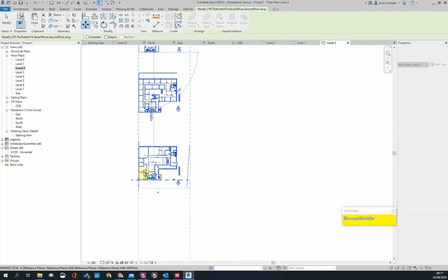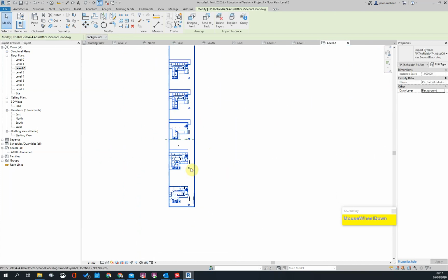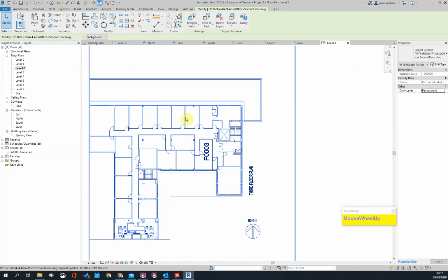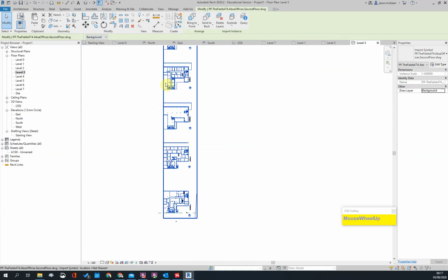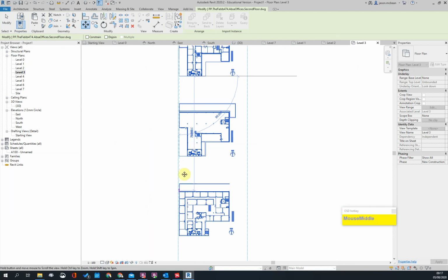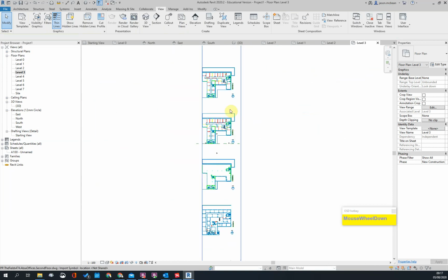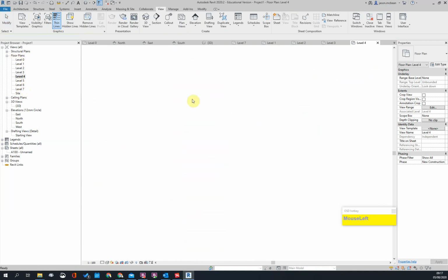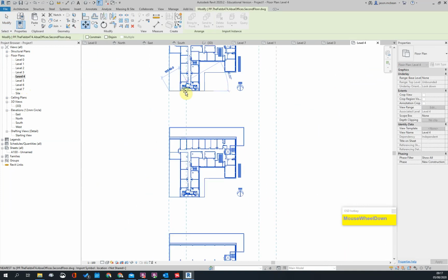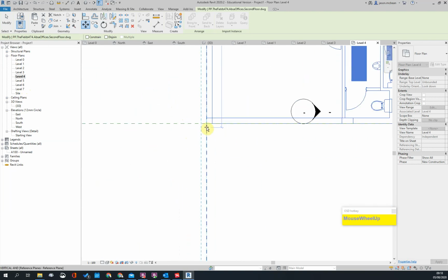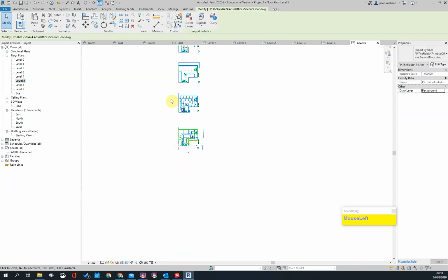Look, there might be some fine tuning later on, but in essence, all that you want to start doing is establishing which walls will go right up to the roof, which walls will only finish between levels. So that's what I'm doing now. So I'm setting up all these levels so that we've got good information to work with. I see there's a balcony around the back here. All right, so pull this back to there. And we can double check this. Just make sure this third floor starts corresponding. So the next one will be fourth floor. So I'm going to go and grab floor 4. Okay, move this. Okay, pull this down. Stop this over here. Okay, and then the last one would be my roof level.